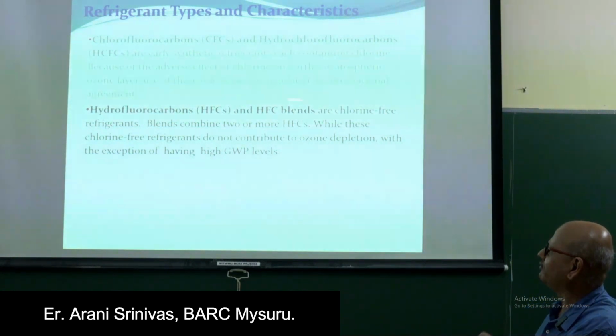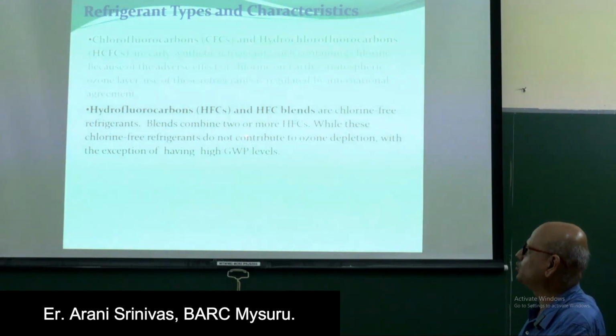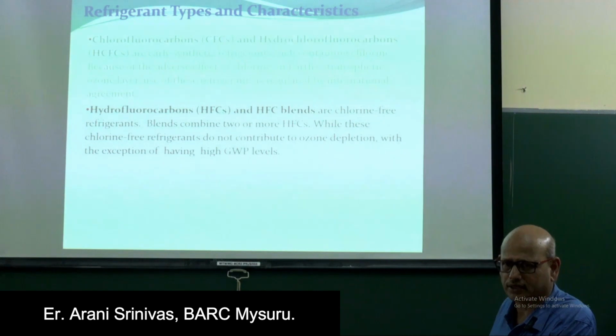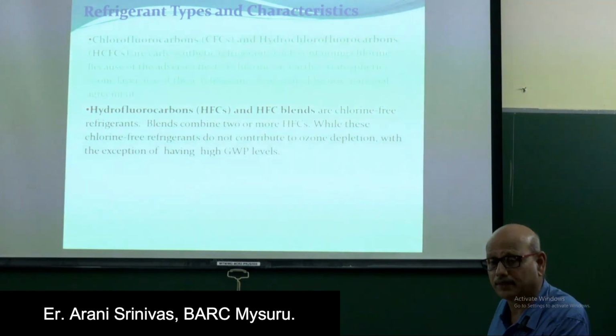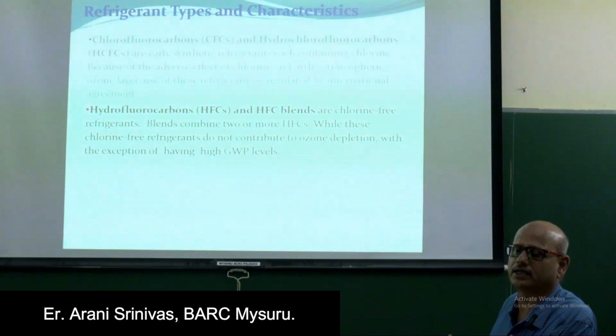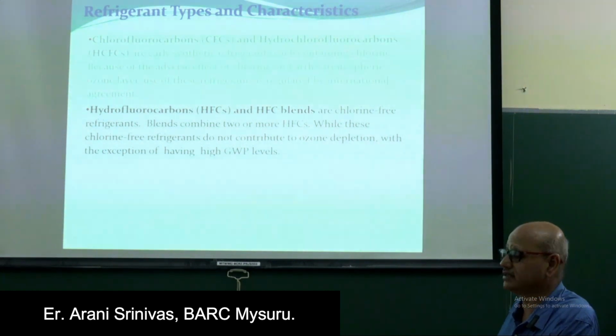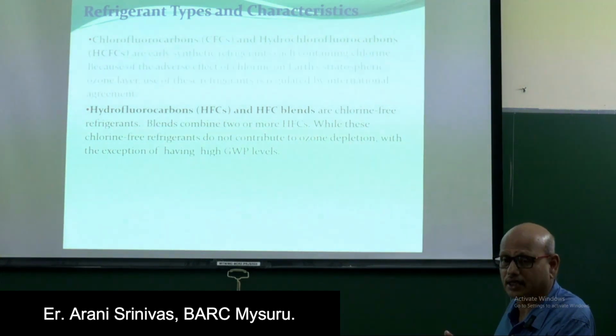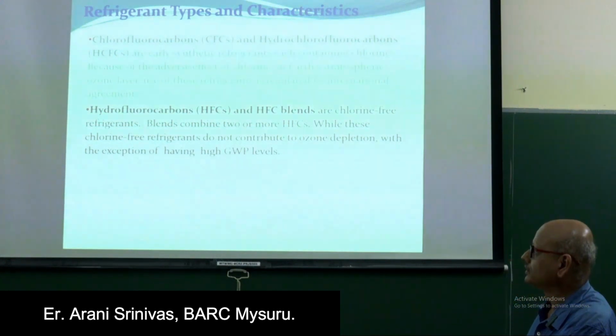HFC blends are chlorine-free refrigerants. Blends combine two or more HFC gases. These chlorine-free refrigerants do not contribute to ozone depletion, with the exception of having a high GWP, which is nothing but global warming potential. So when we tried to reduce ozone layer depletion, ODP, global warming potential increased. HFC gases have more global warming potential.